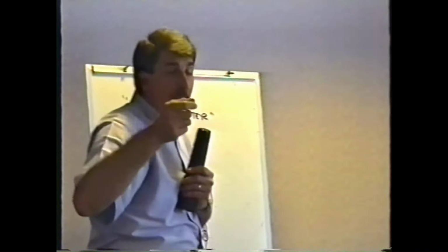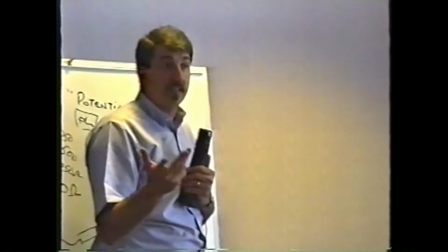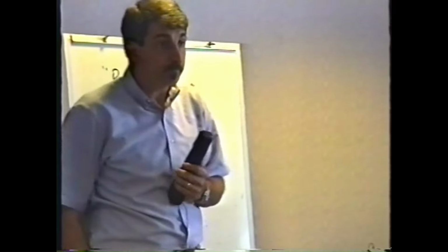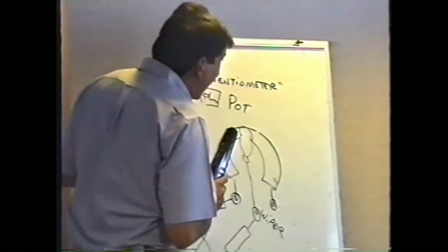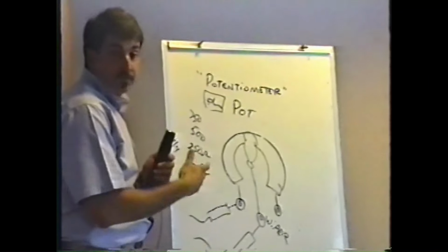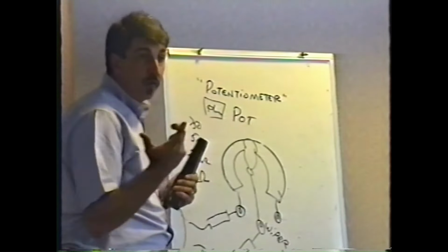That was a really stupid thing to do, because he went out there, saw that it was jumpy, drove 20 miles back to the shop, got another monitor, drove 20 miles back out there to change it. If he had been observant and had noticed, oh, it's getting bigger and smaller, vertical size, that's all it was, just the pot adjustment. Okay, so that's almost all that will ever happen as far as pots are concerned. Like I said, usually I look at them, they're broken in half.